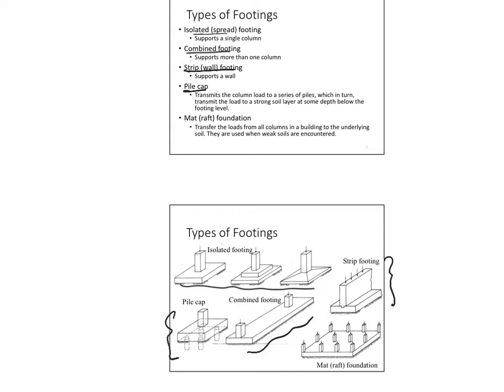This is how it looks like. It's exactly like a footing, but instead of resting on the ground, on the soil, it's resting on several piles that take the load down to a stronger soil, deeper than the surface.